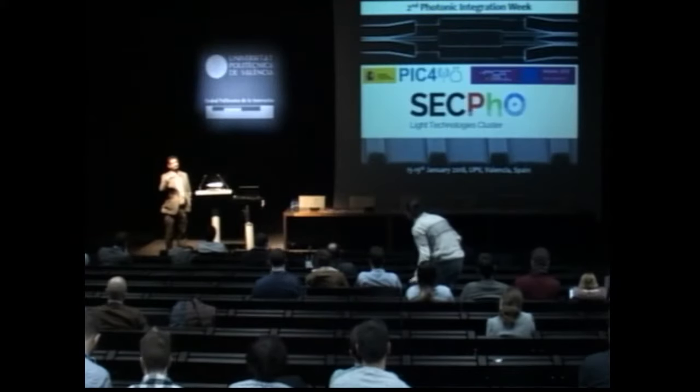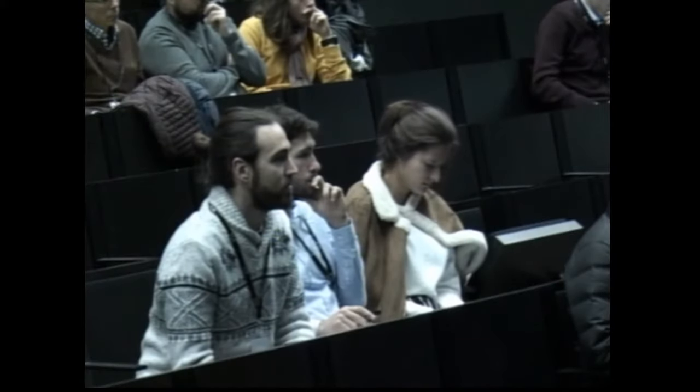Yes. Okay, in order to generate these acoustic waves, you need to have piezoelectricity. Most of the work we have done is in gallium arsenide because the lab is expert in gallium arsenide based material. But in the case of silicon, we also have some people working on that. So you have SOI, for instance, which is not piezoelectric, so you cannot basically generate the acoustic waves there.